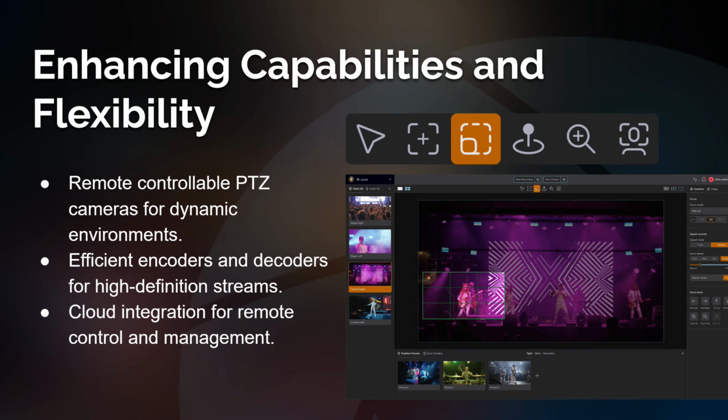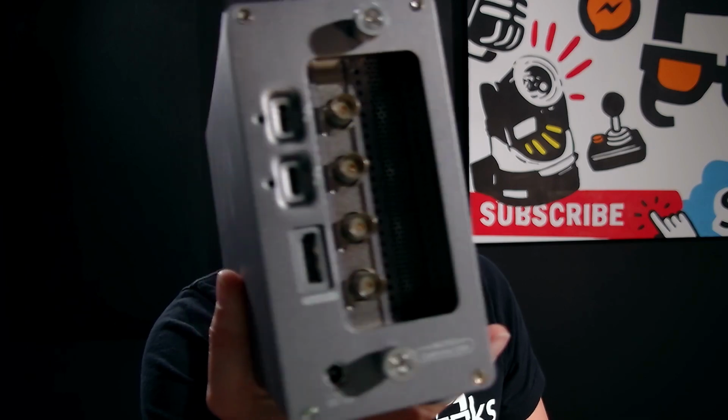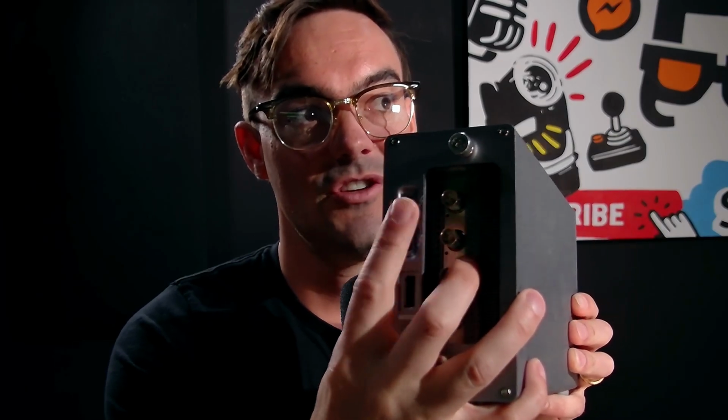Now, I'll show you some hardware encoders and decoders that I have in front of me to give you some real examples. This was the first capture device I ever had, a powerful 4-port SDI capture card that was put into a Thunderbolt enclosure, so you could connect it to your computer. I think these are still used, but maybe not quite as much with IP video. Thunderbolt has a really high bit rate of 40 gigabits, and so you could bring in 3G SDI, 3 gigabits per channel, right? So 3, 6, 12 gigabits of data through this port.